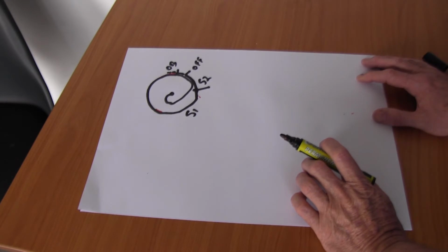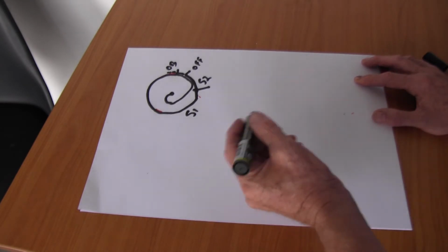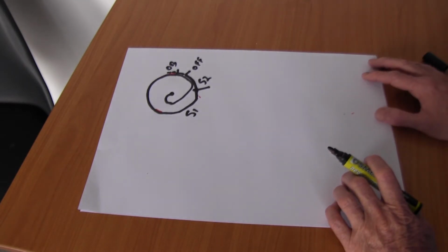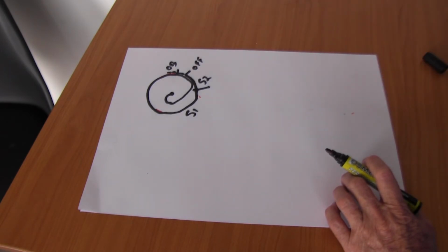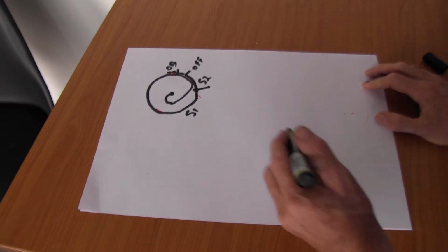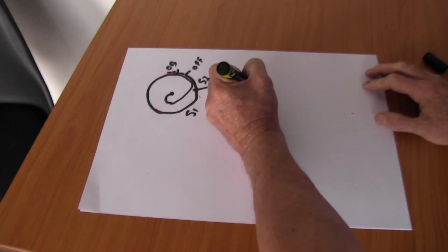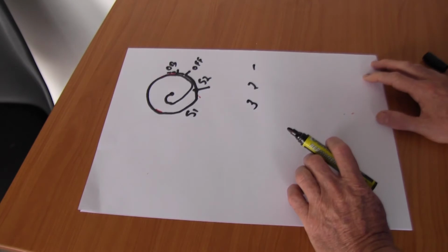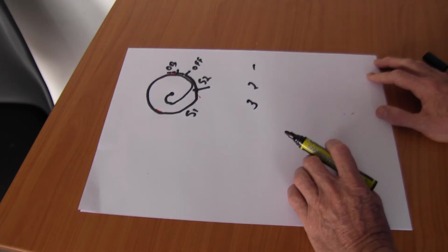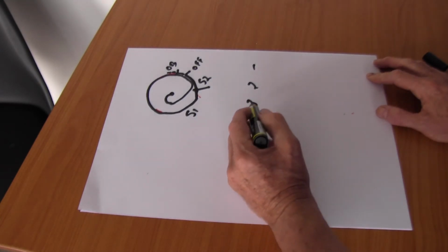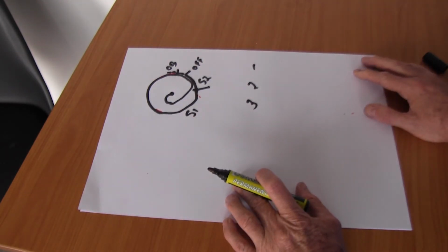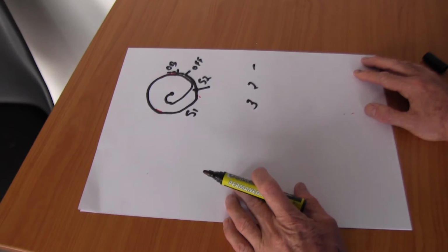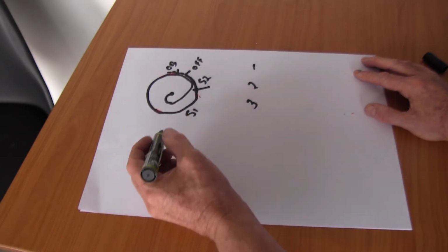So how do we know what those values are? Well, we keep that in a database for that specific cutting process on that material at this amperage. So we might have, say, 2 of these settings here, and we're going to define these in terms of a ratio of the thickness, which will allow us to use it for other materials where we don't have an exact match.